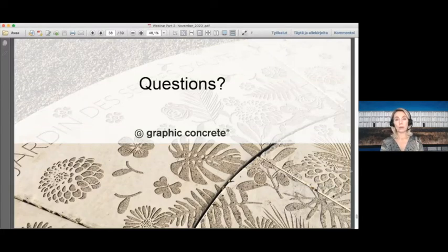So it's good to know that a continuing curve and the same color would be preferable, but of course it depends on the look. If you would like to have dots of darker stones, of course that can be made. But it depends so much on the type of panel and the type of concrete mix. What comes first is the technical aspects of the concrete. It needs to be the right quality, and that would be determined by the mix and the size of the aggregates.